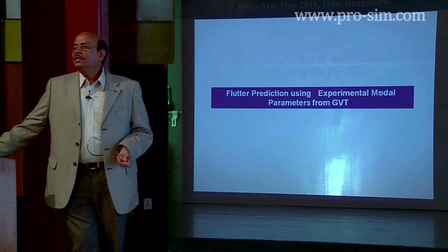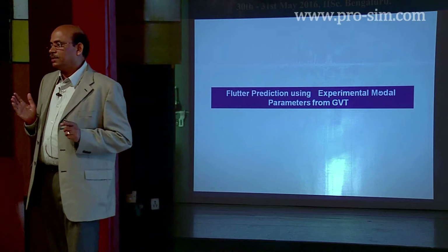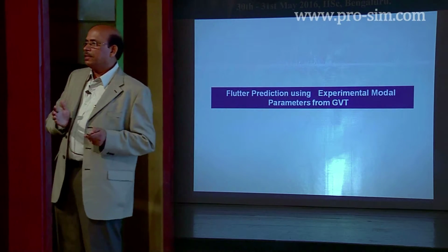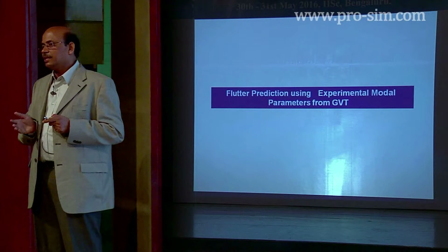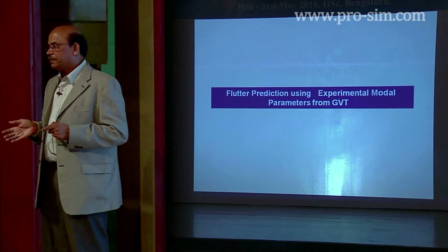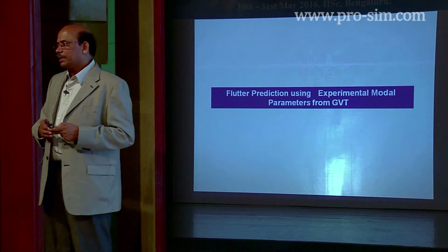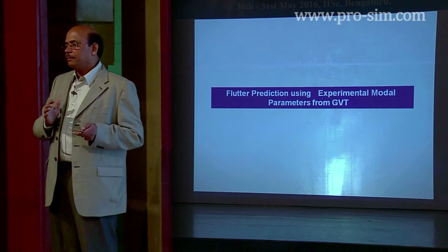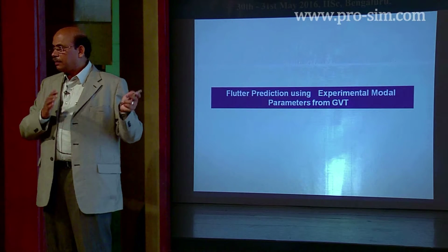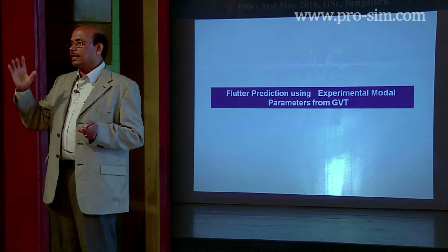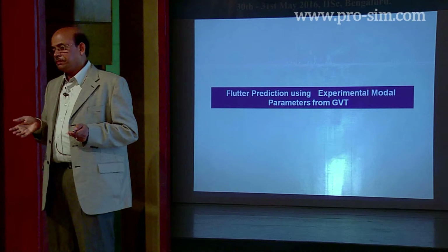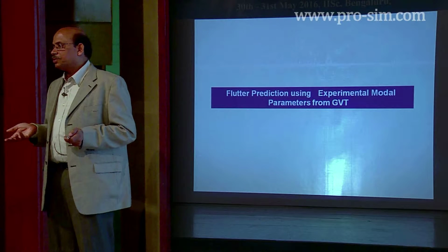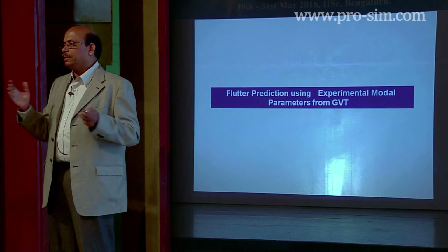Okay, this is one set of methods. We have seen two sets of methods till now. One is the conventional simple linear aerodynamics based methods like the classical method, the state space method and the related applications. Next we saw the high fidelity methods by combining the finite element method. Of course, in the state space method everywhere finite element method is used, but the aerodynamics that is used is very simple. Then we saw the time domain methods wherein we tried to combine the Navier-Stokes equations with the equations of dynamic equilibrium and solve that.